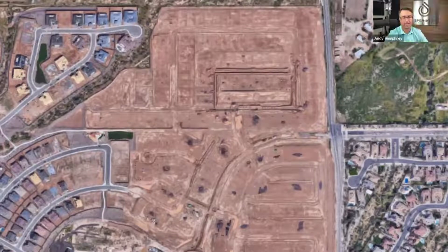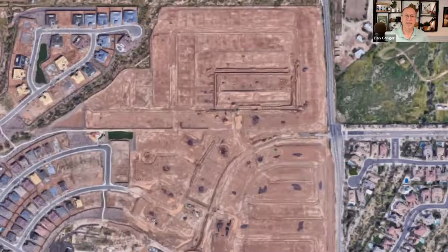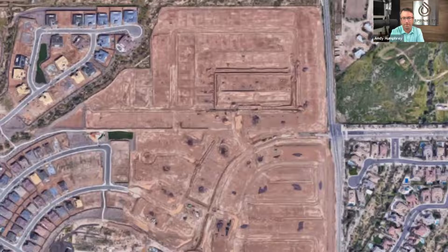Well, it's important to know too that sometimes flat sites have poor radio, and sometimes sites with buildings, radio surprisingly works because it can bounce. So doing a site survey for radio is almost a must. It's critical. You've got to do it because it's very hard to assume, and you're more likely to be wrong.